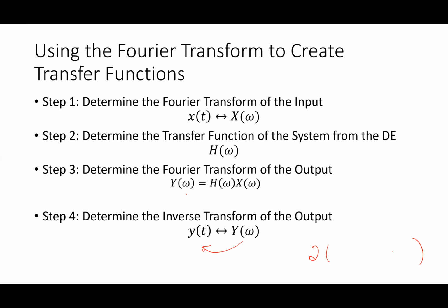There are 2 reasons for multiplying by 2. One is that the Fourier transform assumes complex exponentials where the amplitude is always half of what it is for the true cosine wave. We kind of derived that before. Just remember to bring that factor of 2 in. The way I think about it is that when using the Fourier transform, half of the energy is at the positive frequency and half is at the negative frequency. So multiplying by 2 allows me to do the analysis at one of the frequencies, so I have half the analysis to do, and I just multiply the result by 2.